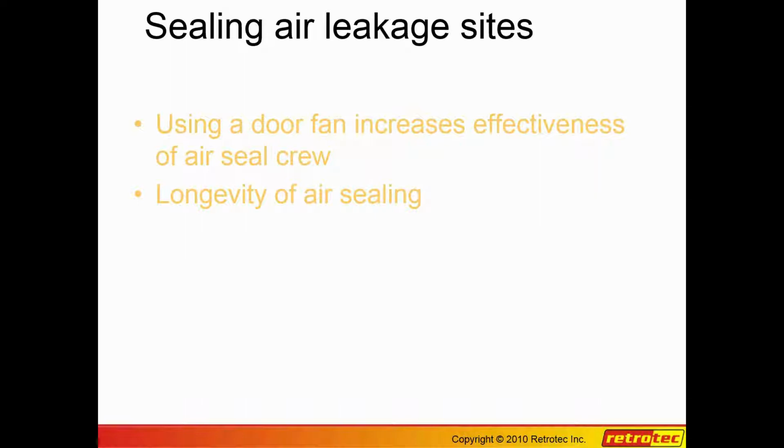But if you were to, let's say, do a whole course of air sealing on the top part of the building, and you do it before and after, then you can see, well, we did this and this and this and it had no effect. We did this and whoa, it went down by 40. So this is the greatest learning tool that you have. The devices we just talked about told you how to find the leaks. This is telling you how to quantify the effectiveness of the sealing.